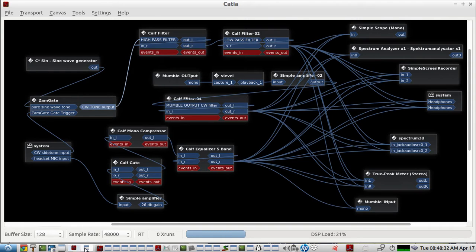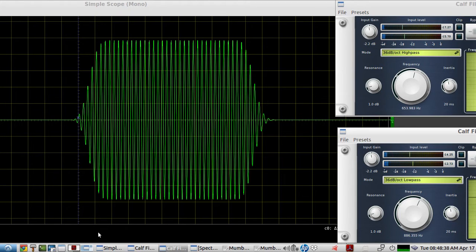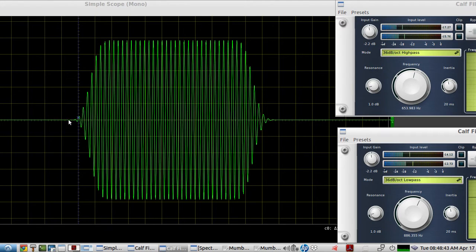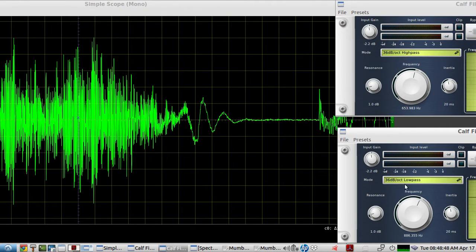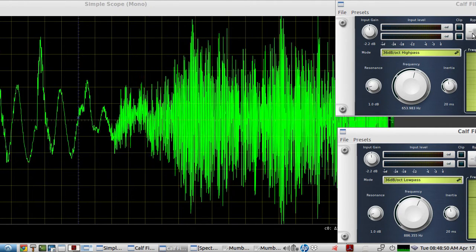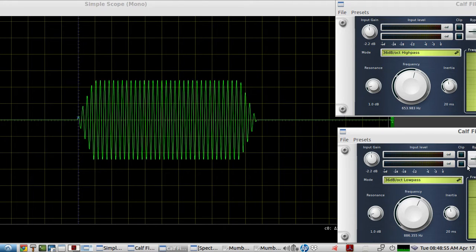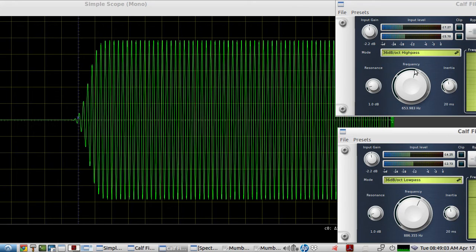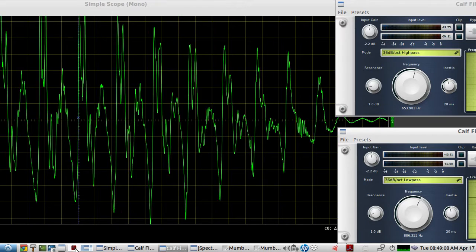So let me show you what that looks like. That's the waveform, and the edges are smoothed out by this high pass and low pass filter. Here's what the CW looks like without it. It's rather trapezoidal. And the filters are optional. I thought it made it sound better. And you can adjust the rise and fall time however you like. Let me show you that.